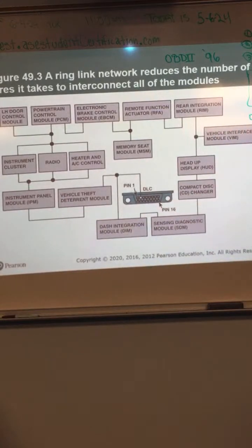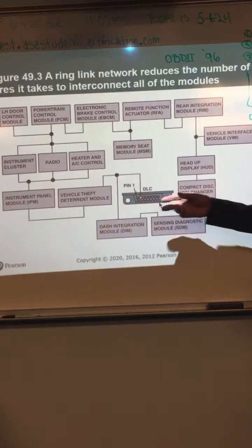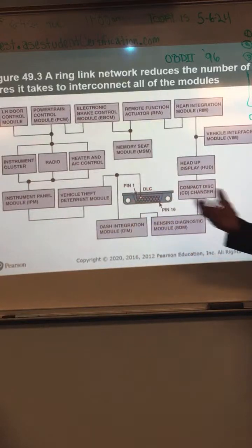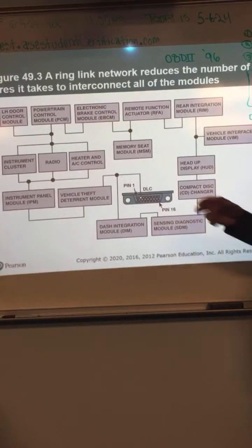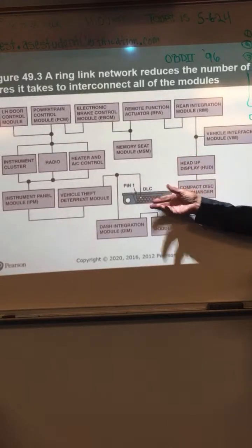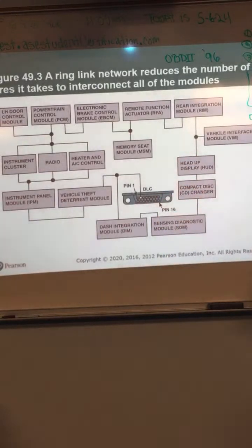The scan tool knows what pins it communicates on. So sometimes, I don't know if you've ever looked up the generic kind of scanners that don't give you a whole lot of information. Sometimes when you first turn them on or plug them in, it will say communicating or something like that. It's trying to figure out what pin it uses, what type of communication system it's using, and it'll figure that out, and then it'll start to give you the information. But sometimes you'll see that come up on the scanner.